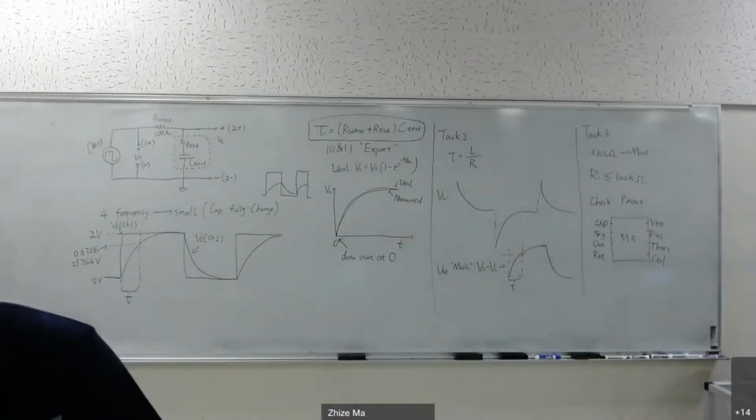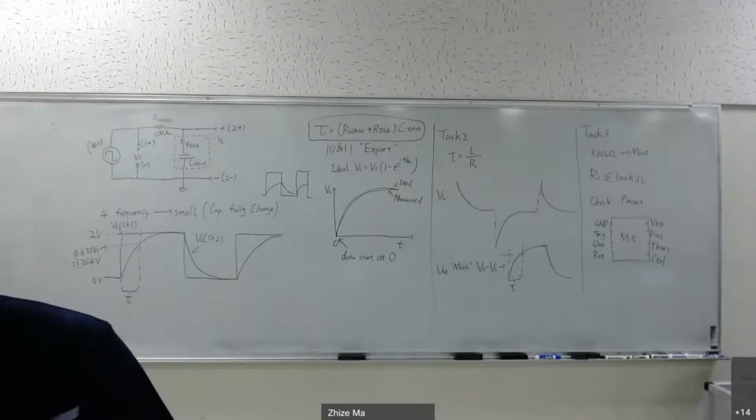All right, I think that's how you build the circuit. If everything is correct, after you build the circuit and push the push button, you will see your LED turn on for 5 seconds, and then it turns off by itself. To measure the time it is on, you need to use channel 1 and channel 2.